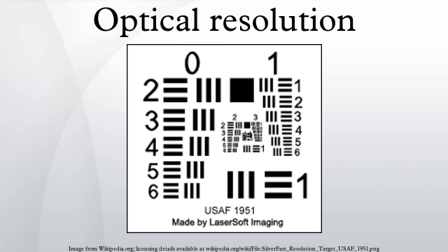For the picture to appear to have approximately the same horizontal and vertical resolution, it should be able to display 228 cycles per line, requiring a bandwidth of 4.28 MHz. If the line width is known, this may be converted directly into cycles per millimeter, the unit of spatial resolution. PAL television system signals transmit frames less often, but the frame contains more lines and is wider, so bandwidth requirements are similar. Note that a discernible line forms one half of a cycle, so 228 cycles and 456 lines are equivalent measures.